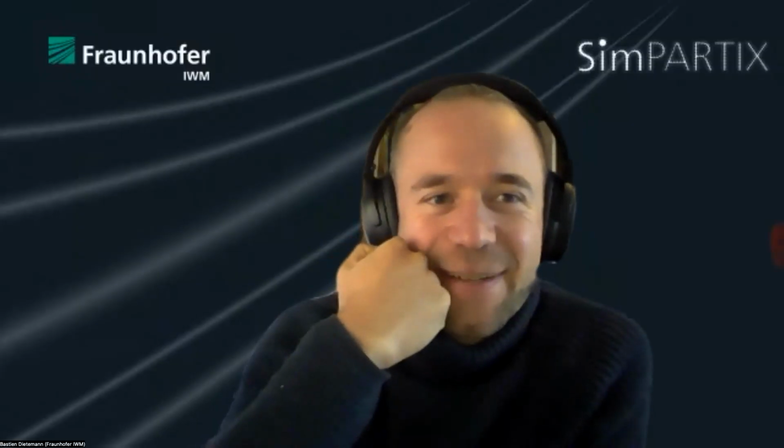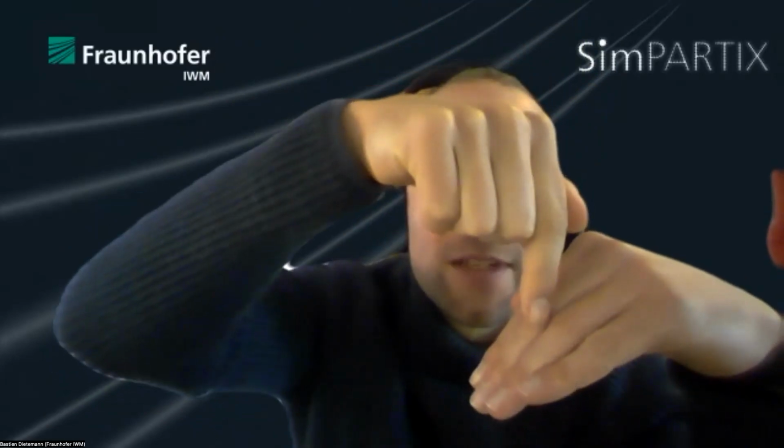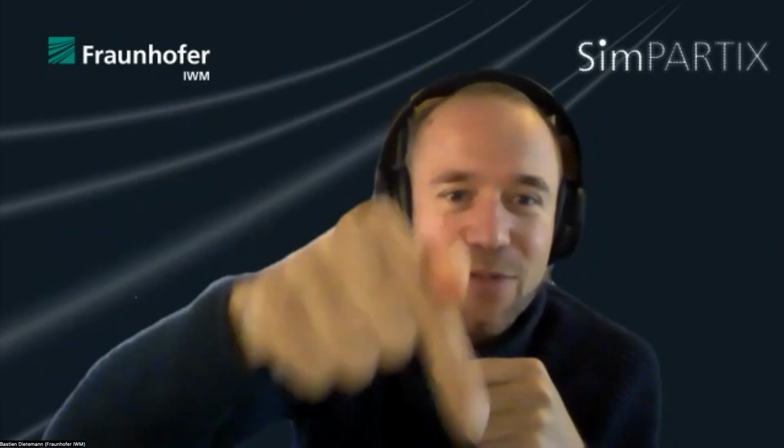Maybe I start. Basically, it's easy. This is already coming out of the discussion of why Daniel is using thousands of rays. You have to imagine that for each of the rays, you have to propagate and inspect: do I meet a surface particle somewhere? No. Oh, there's a surface particle. Then compute the new angle and propagate further. And at every propagation step: do I meet a new SPH particle? No, yes, no. So it's basically propagating through every particle and then estimating. Imagine my powder bed, it's going deep into the powder bed. It's just a complex projection.